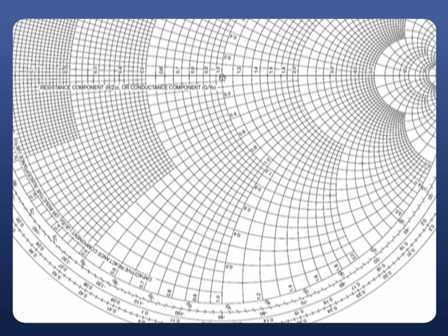Similarly, from the center point of the Smith chart to the extreme left is nothing but the point of short circuit. So when we are moving from the center point of the Smith chart to the extreme left point of short circuit, that particular line is always said to be the V minimum line and I maximum line, that the current will be maximum along that particular line.